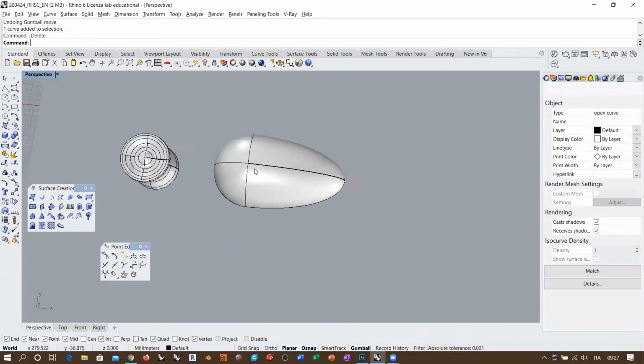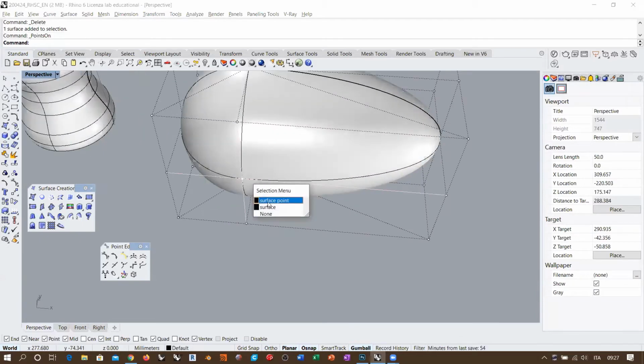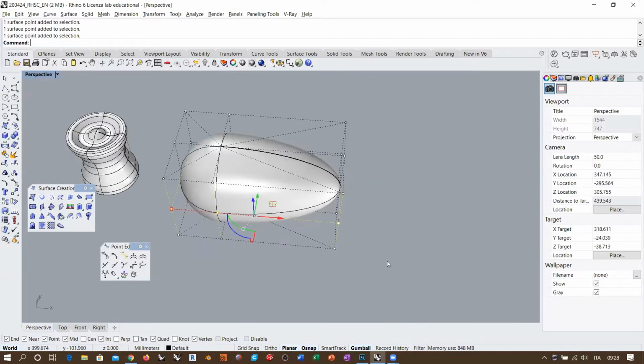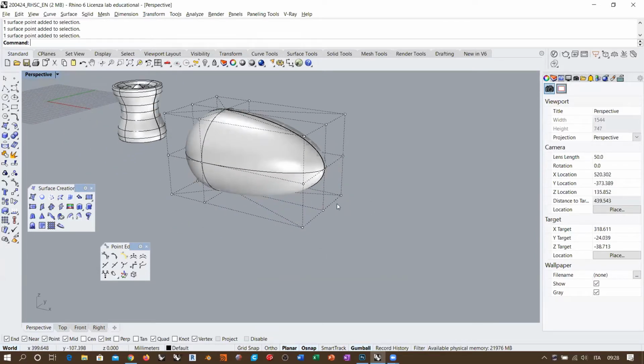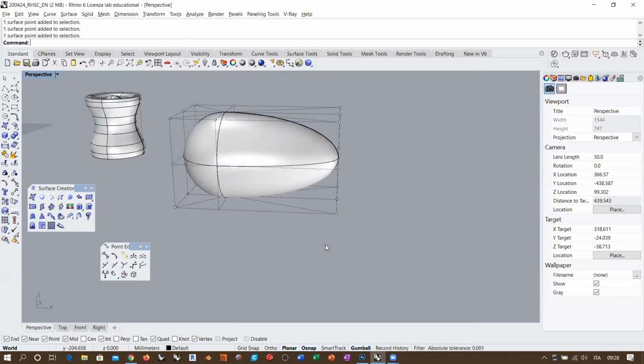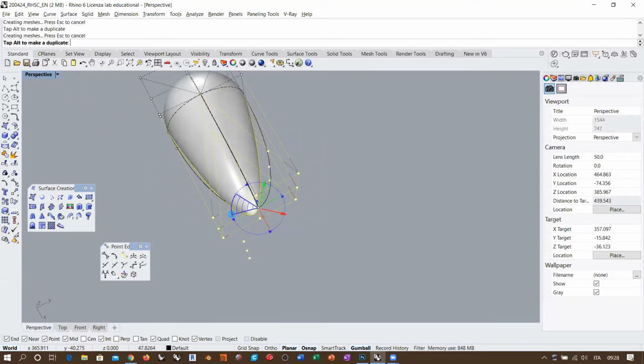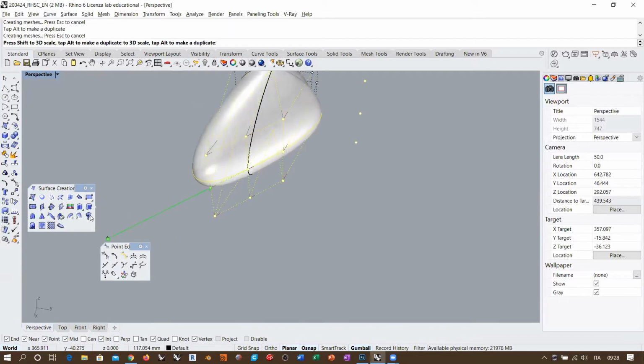So you can think about these quadrant points for our sphere as invisible discontinuity. Okay, so this point here is determining the tangent in this direction, and this point is determining the tangent in the other direction. As long as these 3 points are aligned, you will produce no visible kinks on the surface of the sphere. So here what I'm doing is selecting the whole set of control points that determine somehow the tangency in this kink point. So if I select all this plane of points, I can do whatever I want, including rotation, for example, including scaling like this.